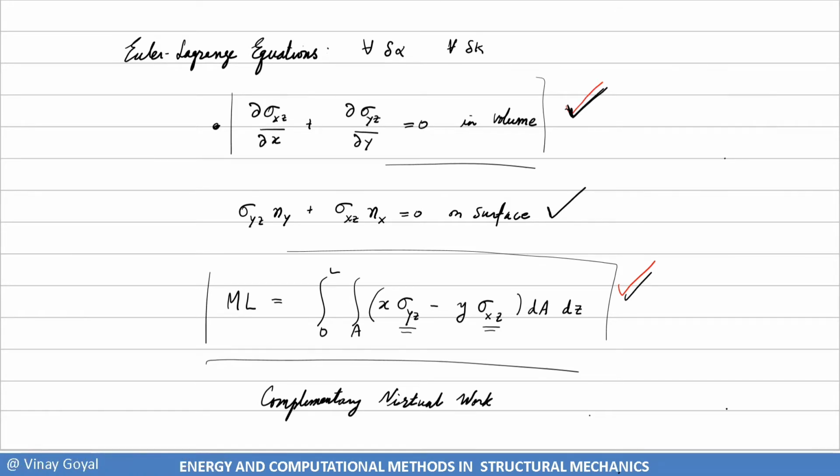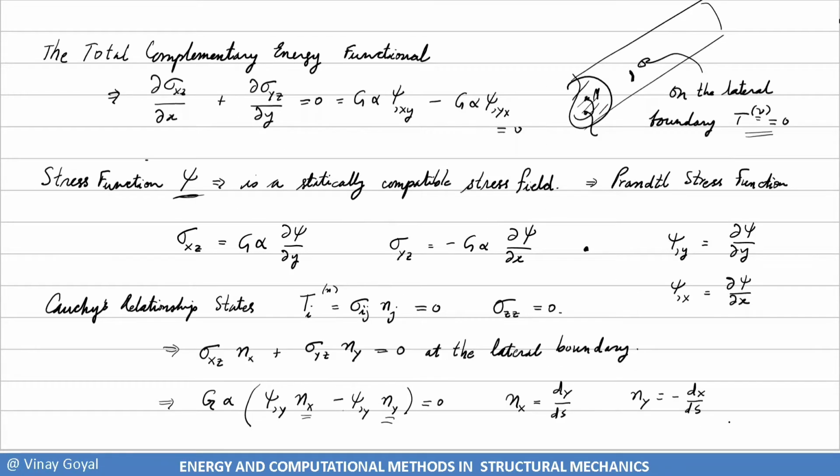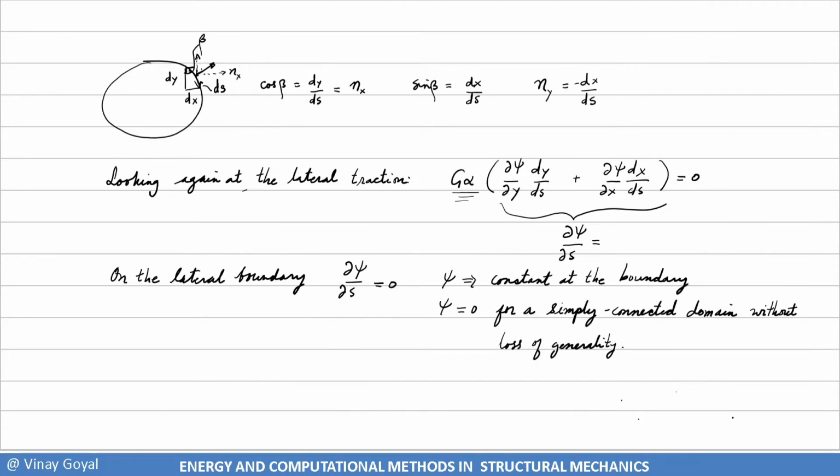I came up with a Prandtl stress function that satisfied this and this exactly. If you worked on the Airy stress function for two-dimensional problems, this is a very similar way. This is similar to the Airy stress function in that I'm satisfying the governing equations exactly how I want it. So with that said, now we can start expanding a little bit more, if you don't mind.